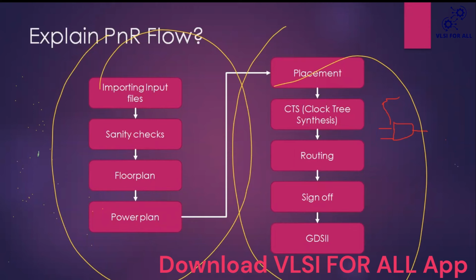In real experience, people will try to fix hold violations after routing instead of before routing, because during routing some nets will get detours. Due to that detour, more delay will get added into that path. So that's why they try to fix after routing. The violation is much more, but anyway we have to fix after CTS only. After routing comes the sign off stage.